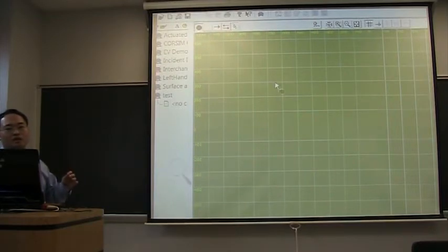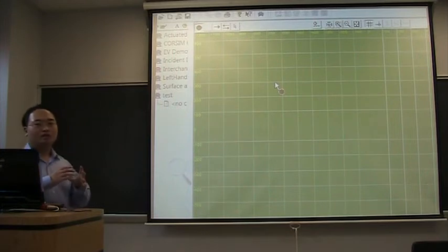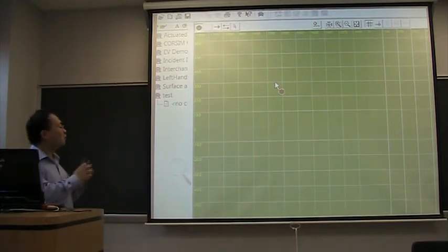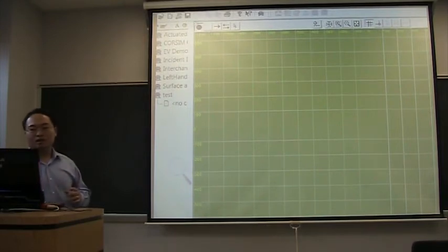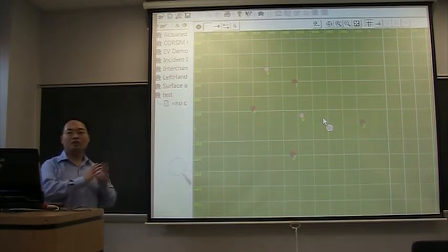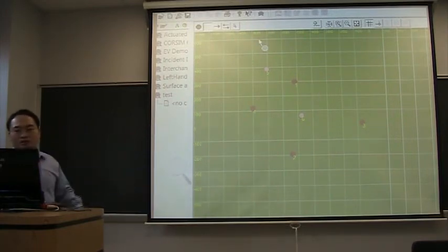The black one means a node that is not on the freeway, which is a NETSIM node. So I can click this and create several nodes. And this white one is a FRESIM node, which indicates the nodes that are used in freeways. So they are of different colors, as you can see.